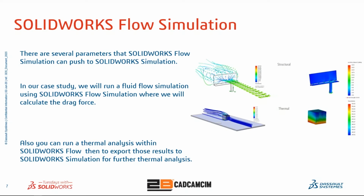Okay, another type of study that uses this combination of Flow Simulation and Simulation is when you have thermal analysis within SolidWorks Flow Simulation, and you export those results to SolidWorks Simulation for a thermal analysis study, to test the effect of rising heat on your model in terms of deformation, stresses or strain.